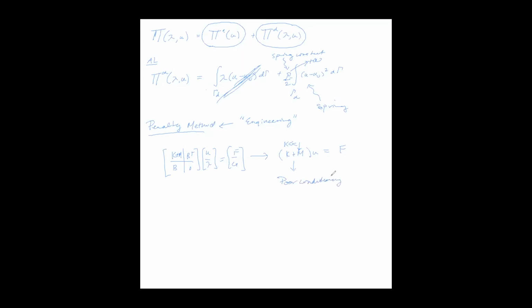Well, another complication that arises with using the penalty method, just from generally using it, is that it's very difficult to validate because, like you said, you want to be able to enforce a certain boundary, and then you don't really know where your boundaries are actually in appropriate contact, or where they've overclosed, or where they're so far away from each other they really haven't even touched. And so validating that model is extremely difficult as well.